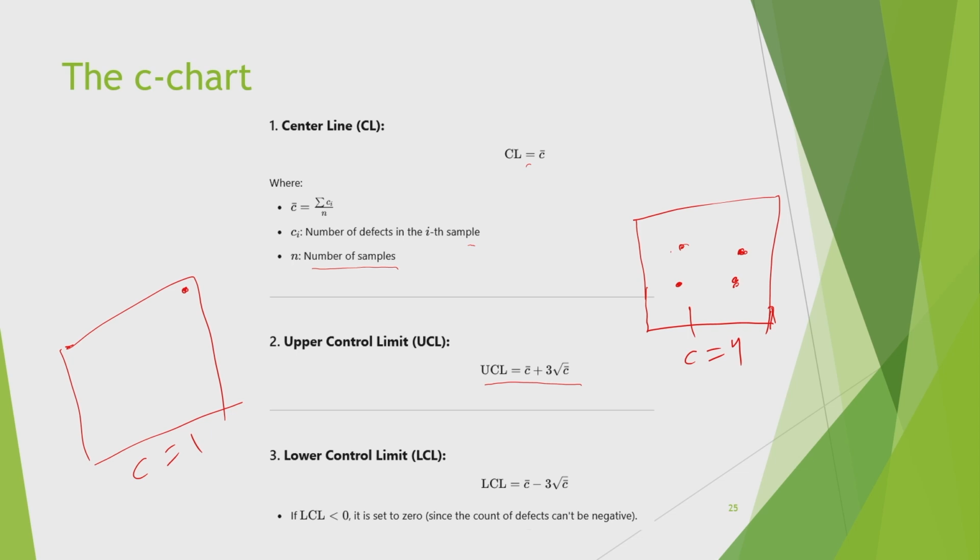So like that we make a control chart, and through the control chart we decide whether the process is under control or not. When your online data comes in, if it crosses the boundaries of the upper and lower control limits, then you get alerted that something is happening. Otherwise you think that whatever variation there is, it is due to random causes and things are under control. That is the importance of a control chart. It gives you the correct amount of feedback and helps you to control the process.